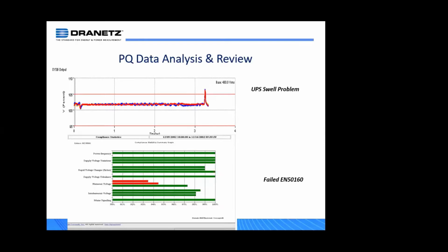And then, of course, compliance. This is a classic that's been around for years, EN 50160, really based out of Europe, that basically shows if you're compliant with these categories here. We can clearly see that in this particular example, we were not compliant with harmonics. But it can extend beyond EN 50160. What we commonly see here is compliance for THD, usually based on 519. So those are the types of monitoring that you have.